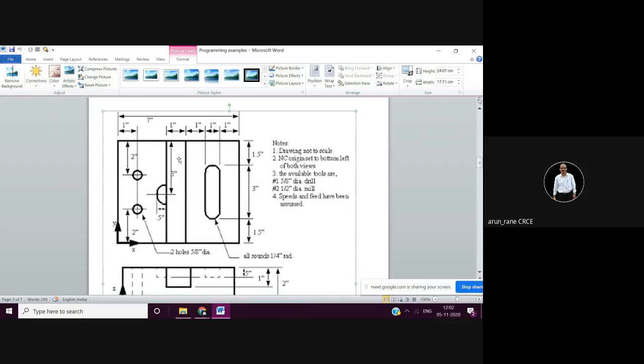And not two passes, you'll have to go for three passes, because normally for the distance that the tool travels, you have to take 80% of the diameter. If this is exactly 1 inch and you are using a half inch cutter, half inch like this, half inch, then in between you will get a ridge, a line.